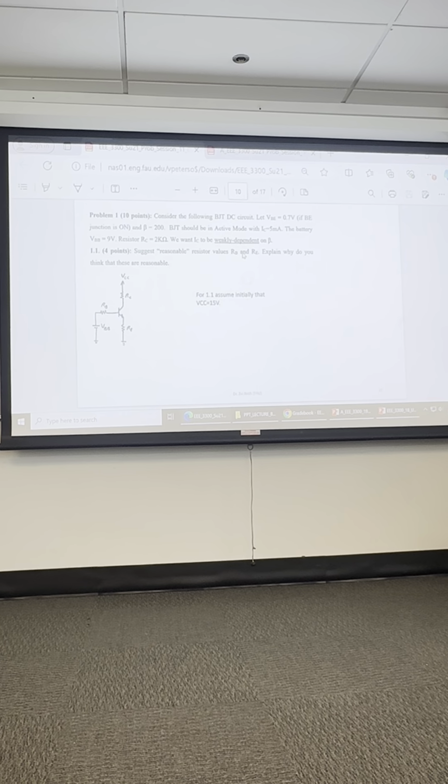So you decided, I know that R_E equal 30K, not such a good number. And the reason is because for R_E equal 30K, R_B is going to be an unusual number. The circuit may not work. So again, you can work on this type of problem somewhere.